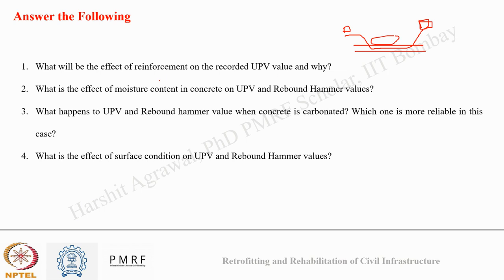So in such cases, we need to apply a proper correction factor when there is reinforcement present near the UPV testing, or if possible, we should avoid the area where there are reinforcements. Now, second is, what is the effect of moisture content?